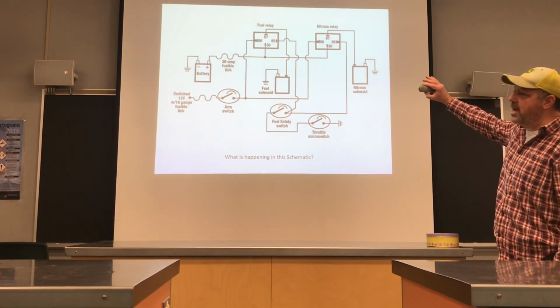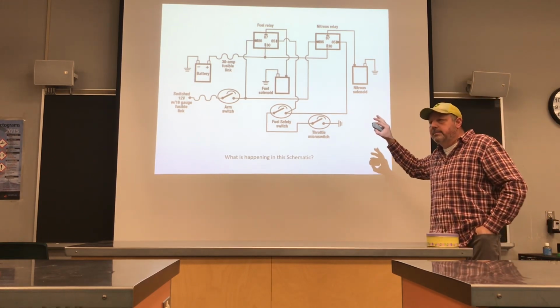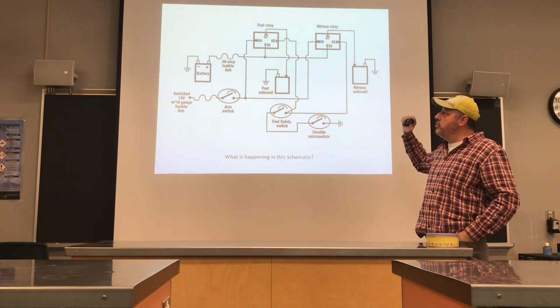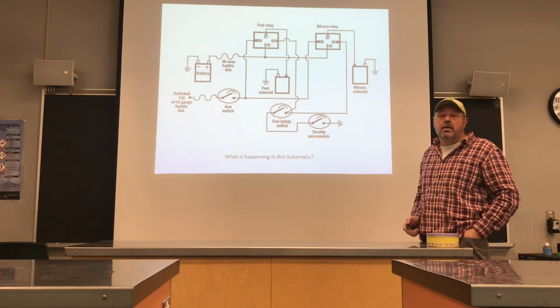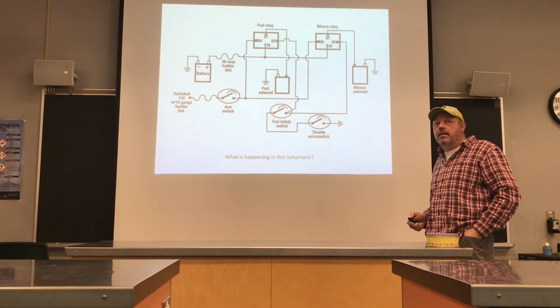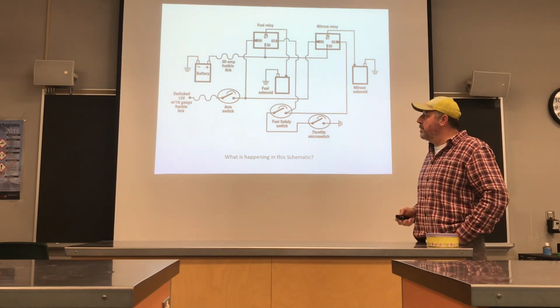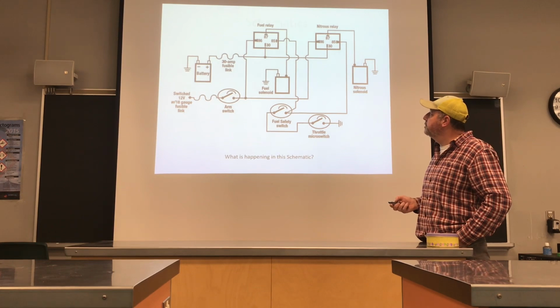So in this example, we're controlling the negative or the ground side of the relay, as opposed to our headlights, where we were controlling the power side of the control, or the control power on that coil, sorry, for the relay.